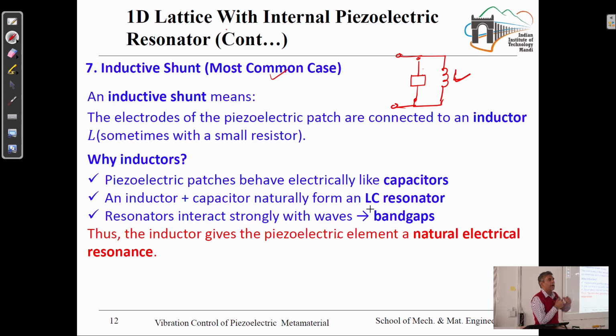And since we have higher frequency vibrations and lower frequency vibrations, we have to deal with all frequency vibrations. In the starting I told you that the periodic structure can diminish the higher frequency waves, but it cannot diminish the low frequency waves, right. How it can, we will see later. We are talking at the moment about low frequency waves, because low frequency waves are very critical, particularly for very thin structures where we cannot add external masses, because external mass makes the system heavy, and also it cannot be controlled.